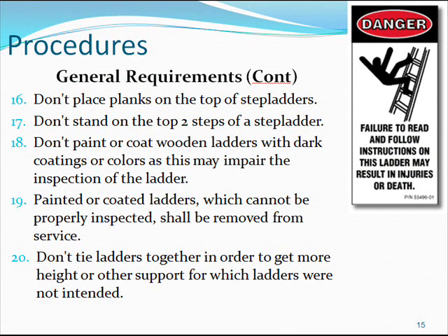Do not place planks on the top of step ladders. Do not stand on the 2 top steps of the step ladder. Do not paint or coat wooden ladders with dark coatings or colors. This may impair the inspection of the ladder. Painted or coated ladders which cannot be properly inspected shall be removed from service. Do not tie ladders together in order to get more height or support for which ladders were not intended.